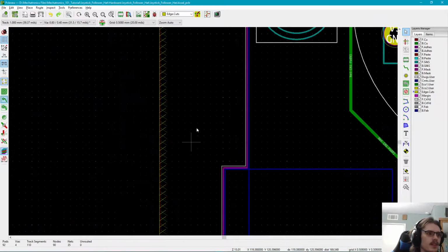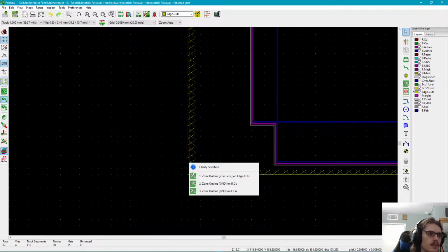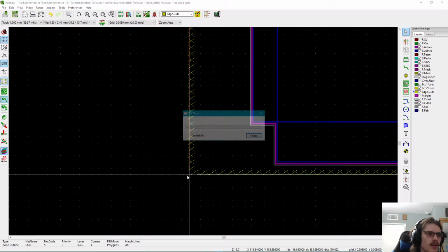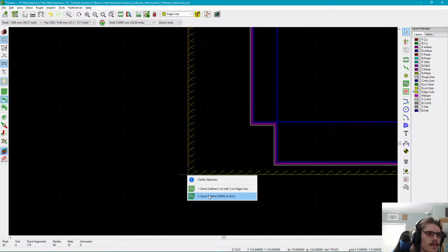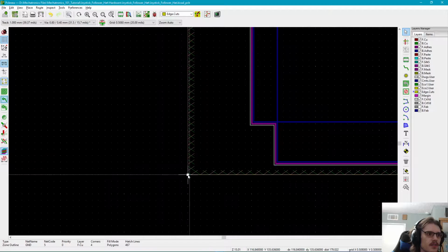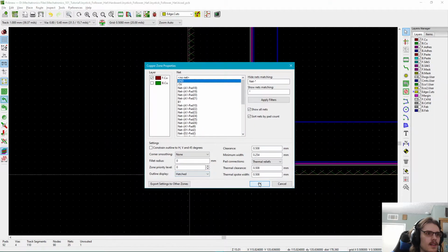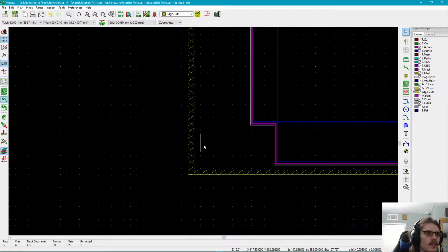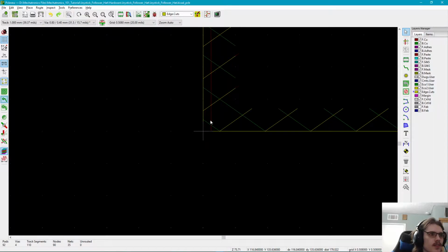Let's see. Okay. If there's ever something not selecting, just hit double escape. Okay. Holding Control, moving it to the side. Left click, and then we want the front. Holding Control, move to the side. Okay. It's all right. Always hit Control Z if something disappears and you don't want it to. There we go.